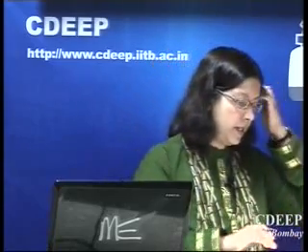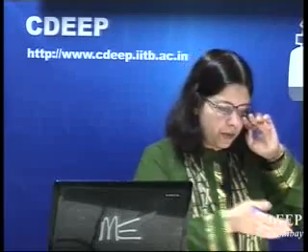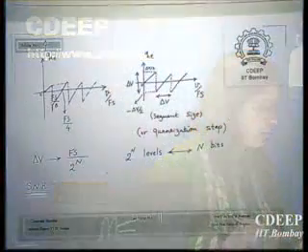It's random only if your signal is very active, in the sense that it can take all values over a long time with a uniform distribution. Then you will get a quantization error close to random, which will eventually be a random noise. This is not exactly the same, however in this analysis we assume it is, so that we can simplify it.